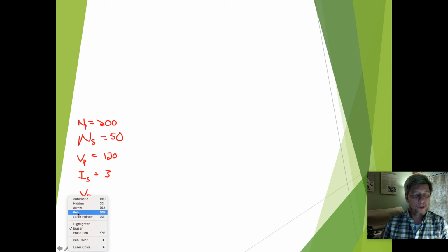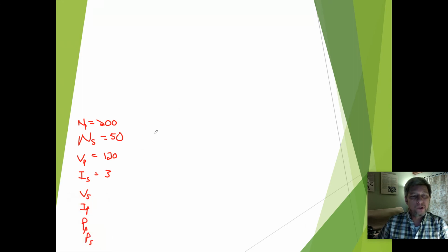So 200 over 50 is going to equal 120 over VS. We're looking for the secondary voltage here.